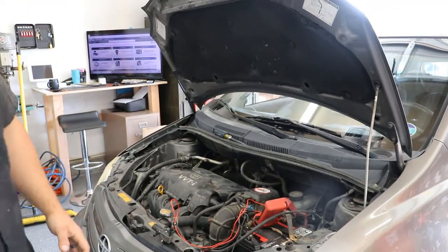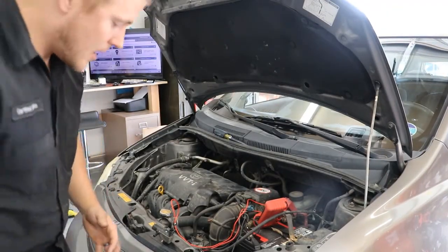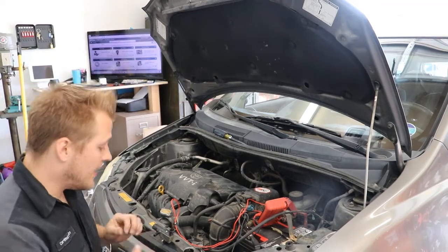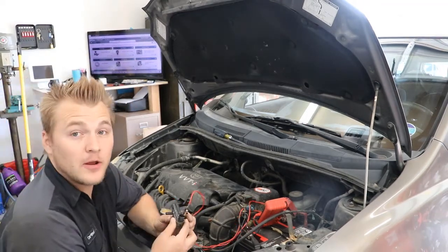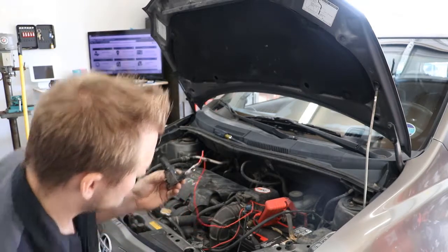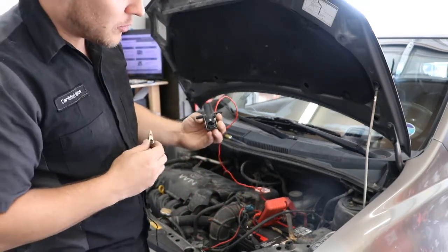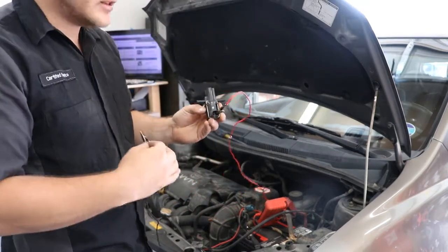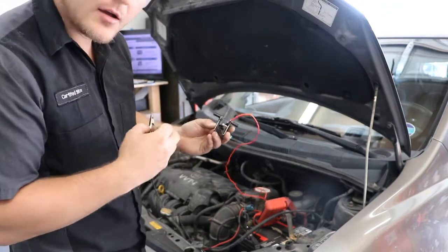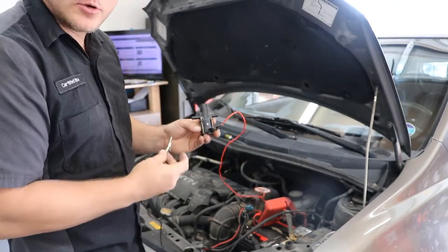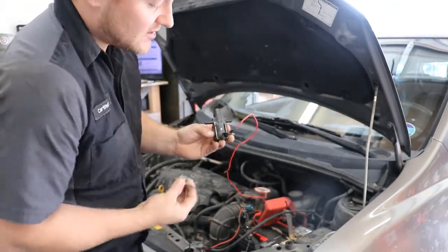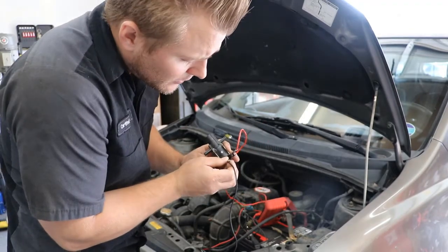So I'm also going to do a small voltage test to see if the solenoid is functioning. Alright, guys, so now we're going to do a quick test on the solenoid itself. I have hooked up a positive terminal to the battery and a negative terminal, and I'm going to touch it to each of the prongs in here just gently, and you should hear a click or a little tick or a knock of the solenoid functioning, opening and closing. This is a way to test if the solenoid is good. So now we're going to test it and feel it.